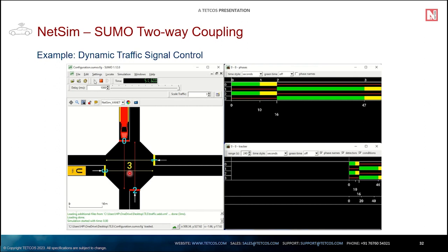At the 46th second, the signal shifts to phase 3, which lasts for 6 seconds, during which it switches to yellow in the EW lane and remains at red in the NS lane. The cycle again continues by shifting to phase 0 at the 52nd second.